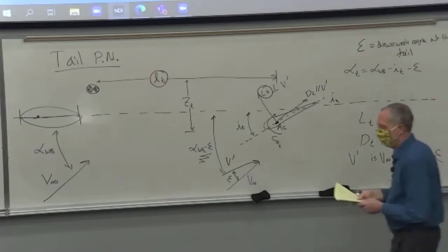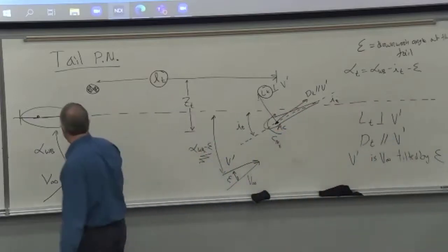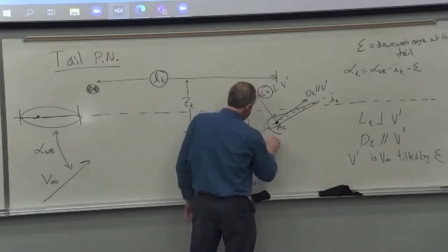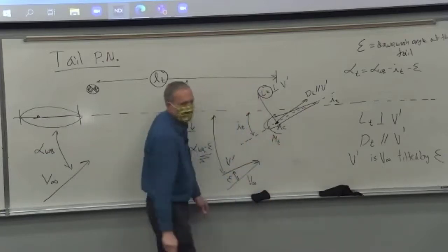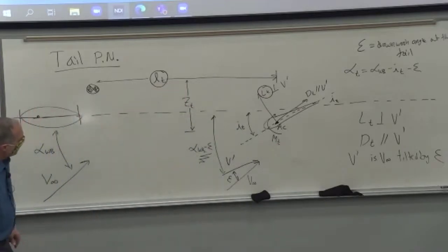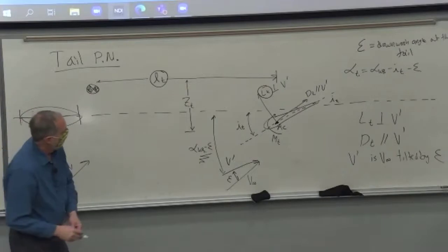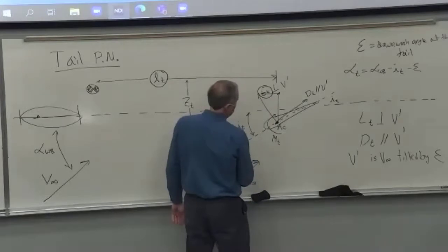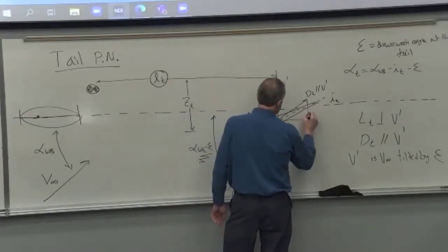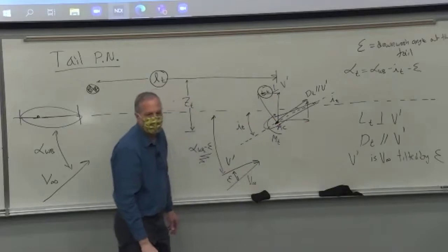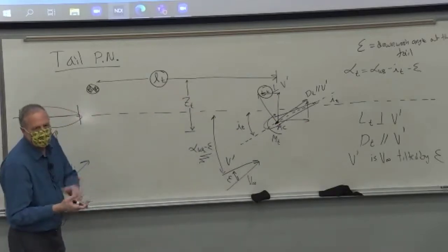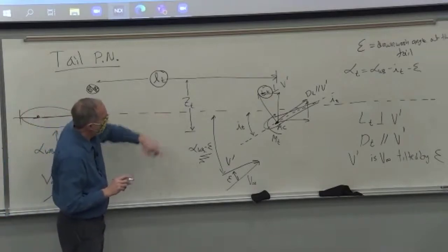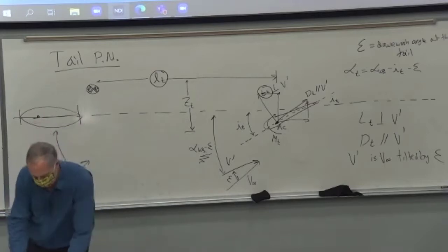And so the tail moment is going to be the shear couple. I should have called this M. We haven't coefficientized it yet. I don't even know if that's a word, but I haven't turned it into a coefficient. So we're going to have the pure couple plus the two components of the lift and drag. So it's just the geometry and the moment arms and all that junk. So we get the components of that times the Z's and the L's, and we get a big formula. So I'm going to write that up on the board, and then we're going to make it simple.